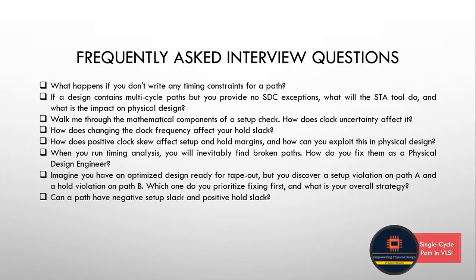Okay. Now the next question is, if a design contains multi-cycle paths but you provide no SDC exception, what will the STA tool do and what is the impact on physical design? Well, to answer that, the tool defaults to a single cycle clock, right? Now, severely over constraining the path in physical design, the tool will waste area and power by aggressively sizing up the buffers, right? And it can also use high leakage cells to meet an impossible one cycle deadline. So we should not do that. That is one of the recommendations.